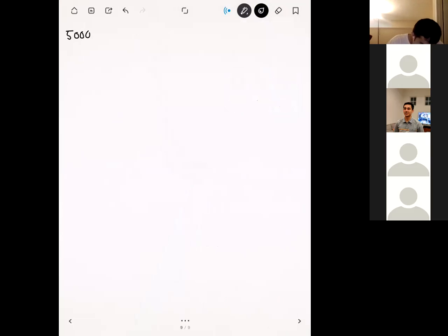So we have 5,000 times 2. Normally we have 2 over L cubed, but L cubed here is just 1. I forgot our 1/5. So we have 1/5 times 2 times U1y minus U2y, plus theta 1 plus theta 2. We had a 1 over L squared there, but since L is equal to 1, we can just change that to 1.